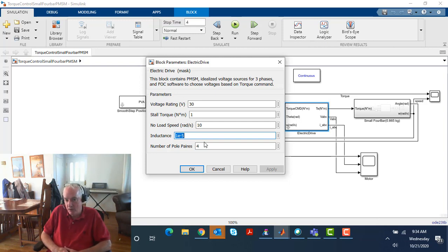Because we know what our maximum torque is, which is the same thing as stall torque. Well, let me be careful about that. Our maximum torque is occurring actually while it's moving. And therefore the stall torque required to produce that will be bigger. But let me get back to the point that we do know what our maximum torques and maximum speeds are. And I'd say at this point, there's a little bit of trial and error, but what's a better tool than Simulink, which allows you to put in these numbers and see if it'll work or not. Is the power of this motor really enough?